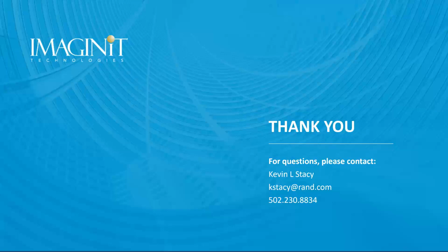Thank you. Just as a quick wrap up, Gladys, as we look back at this translation, the CAD standards and the defining of those CAD standards is the critical portion of any successful translation, and that translation can be done on a small scale, but it always includes a translation table, so old to new, and defining each element within that translation.